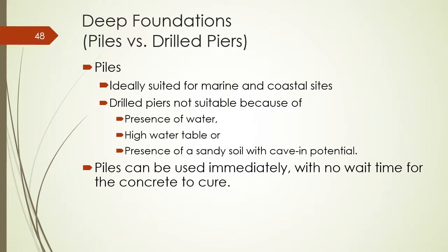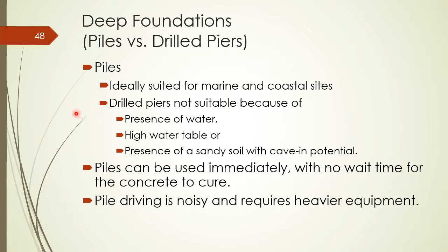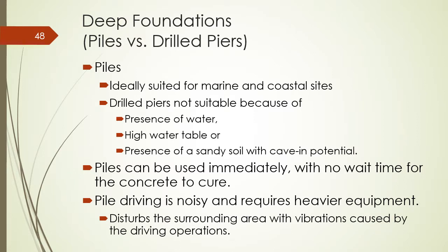And piers, drilled piers, might be good for a low-rise, in expansive soil. Pile driving is noisy and requires heavier equipment, so a drilled pier would be a more suitable alternative because we really don't want to tick off the neighbors.